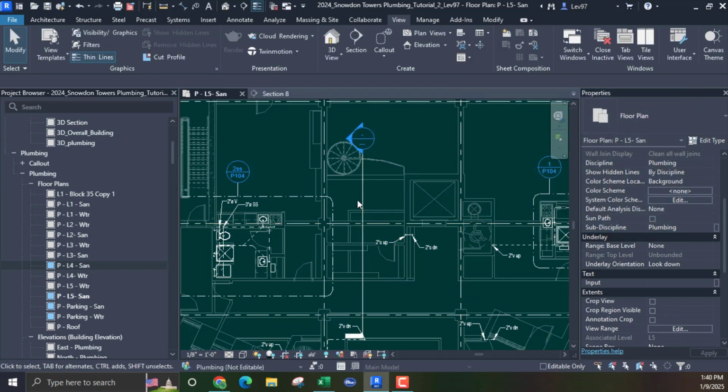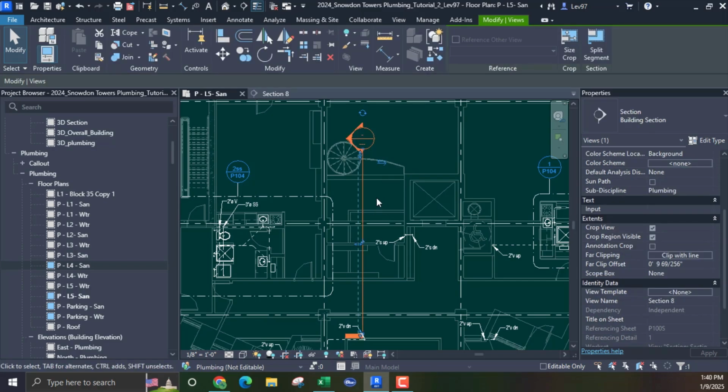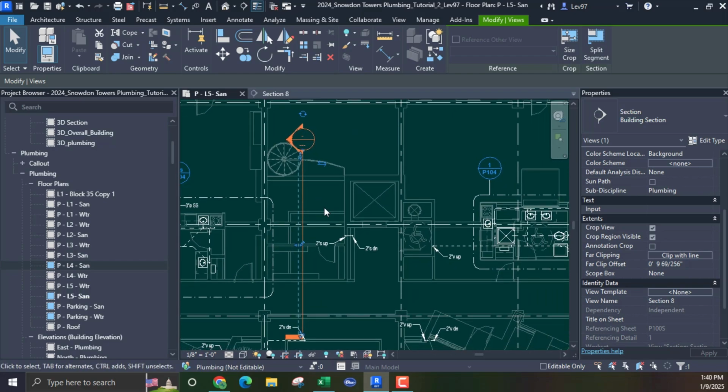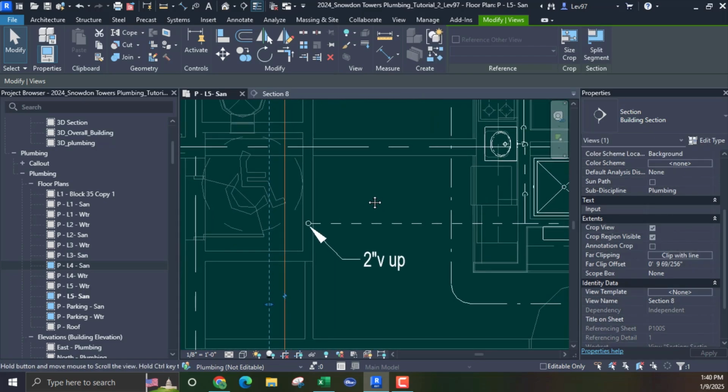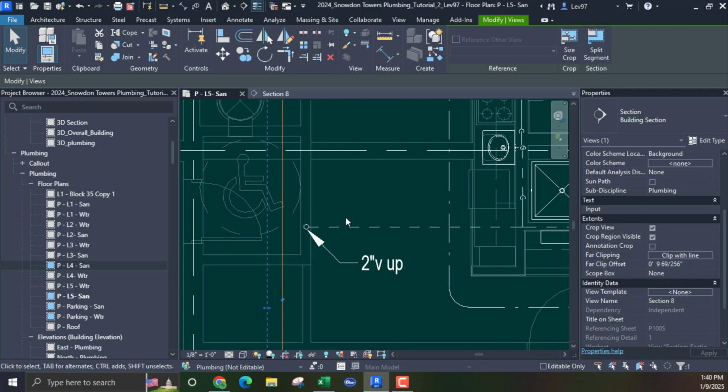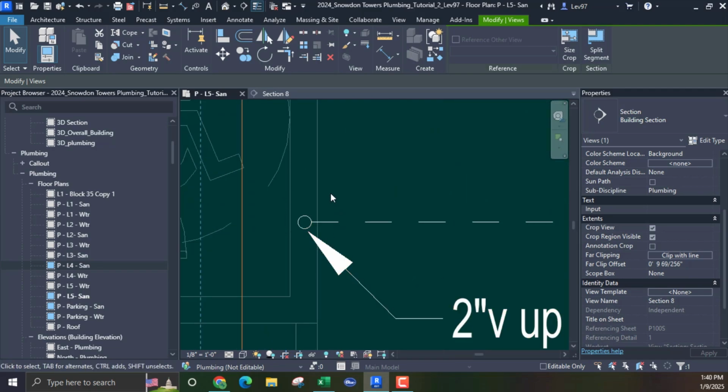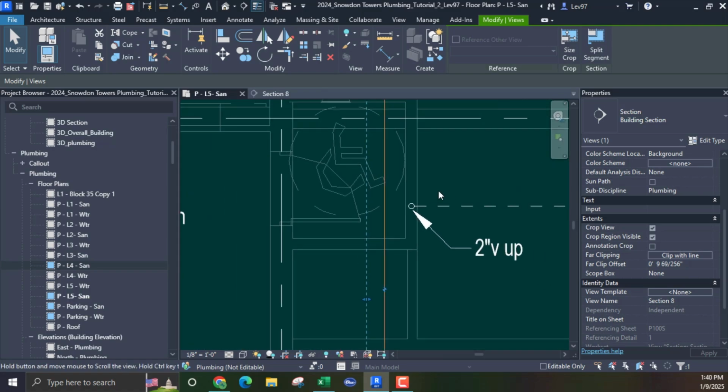So when you're looking at drawings and you want to control your piping, your ducting, you can control it through a view range. And you want to get it as close as possible. The other thing I want to point out in your view range is when you're dealing with pipes and you want to see the pipe symbol going up, right?